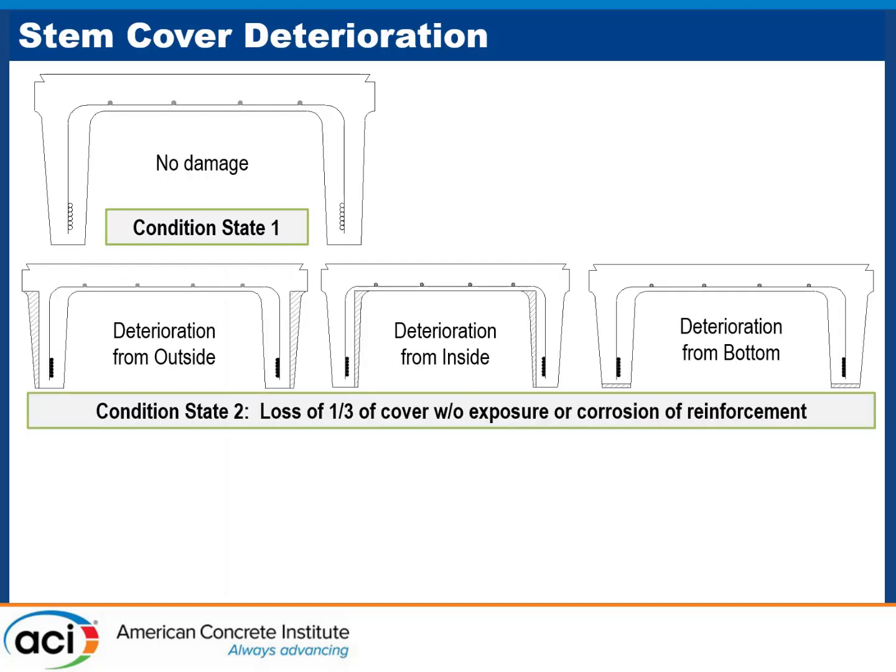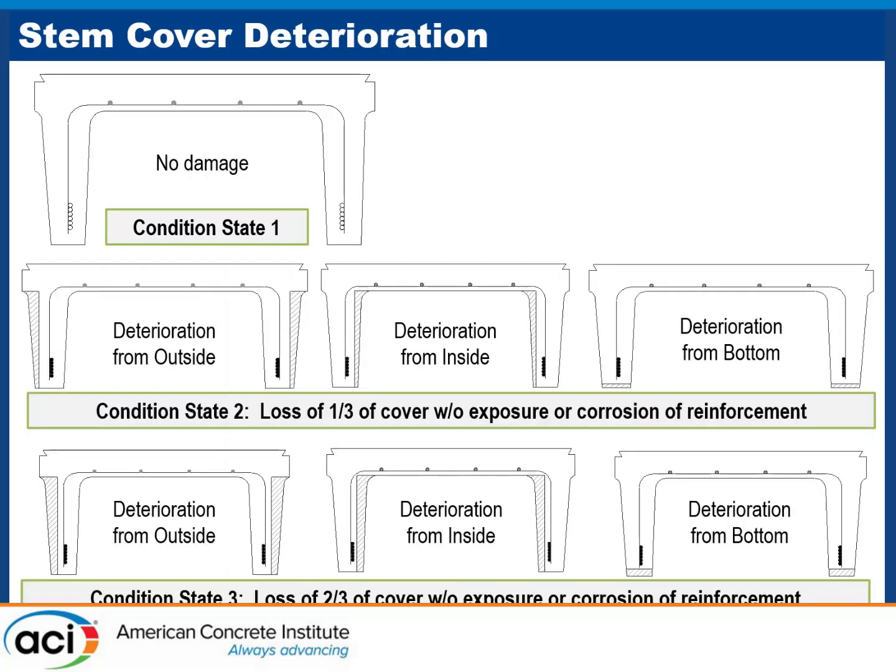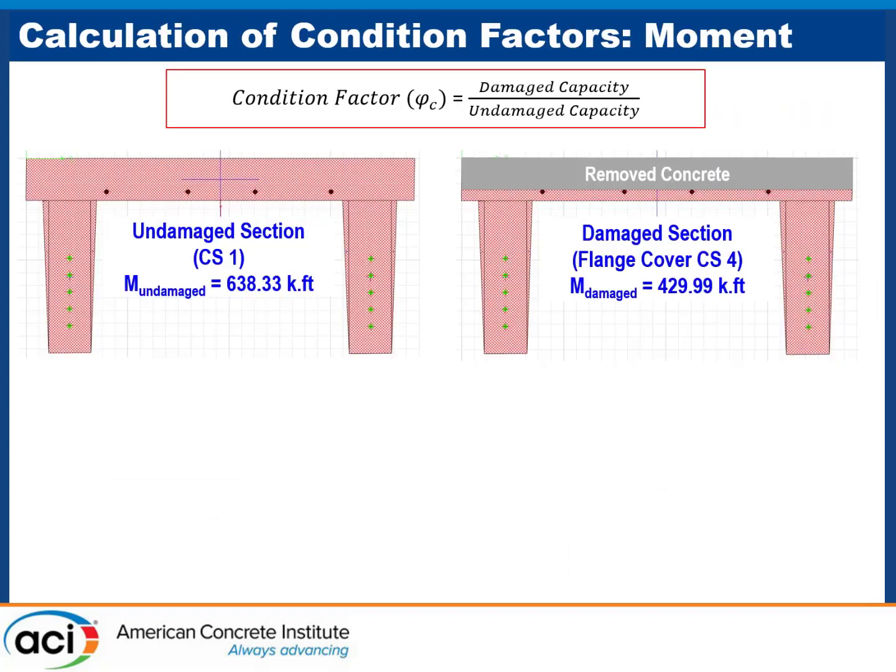And we just didn't come up with those numbers arbitrarily. What we did, we assumed multiple different damage scenarios per damage state or per damage type. We calculated the shear capacity, we calculated the moment capacity of damaged to undamaged one, and we got those ratios. Here is one example.